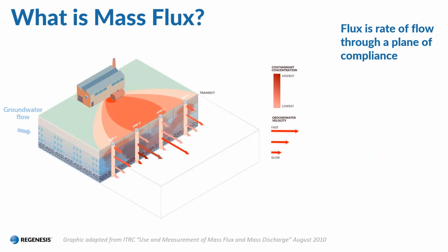What we want to be able to quantify and measure on a remedial scale is where the zones of most mass are that are migrating through our aquifer, because that's what our remedial options, our remedial strategies, are going to address: that actual mass, and not so much the concentration that's present in the aquifer. So we have this complex picture of mass that's distributed unevenly, and that's really what we need to understand in order to do proper groundwater remediation in situ.